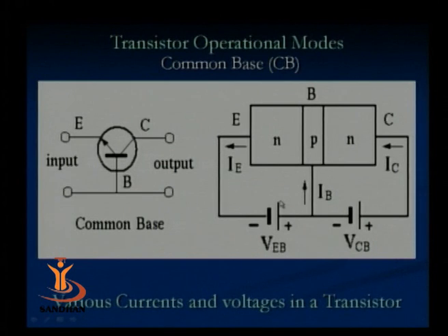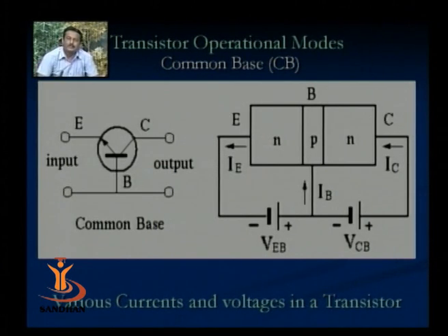Why do we connect them? We know that the transistor cannot perform operation without any energy. So we supply DC energy to it, and normally we refer to it as DC biasing of the transistors. So these two batteries, VEB and VCB, bias the transistor, and they are called the biasing components of the circuit.